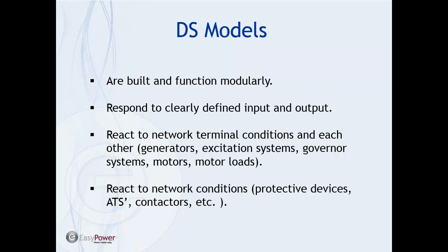So the models are built and function modularly. They respond to clearly defined inputs and outputs. They react to the network via their terminal conditions. That is, the generators, excitation systems, governor systems, motors, and motor loads, they react to the terminal conditions.